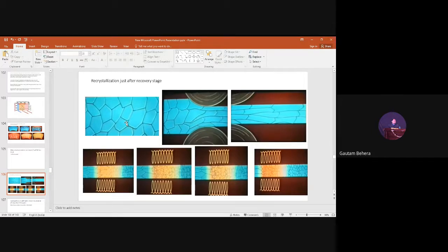But absence of nucleating agent or inoculant gives rise to which kind of structure? Macrostructure in solids. Absence of inoculants, columnar. You are just guessing. Just tell me clearly. Sir, both columnar and equiaxed. Yes, both columnar and equiaxed. Very good. Where will it form columnar and where will it form equiaxed? Sir, at the wall columnar, and at the center equiaxed. Oh God! At the wall it is columnar? Are you sure? Do you remember the figure I have drawn on the green board? At the wall it is equiaxed, and towards the center it is columnar.